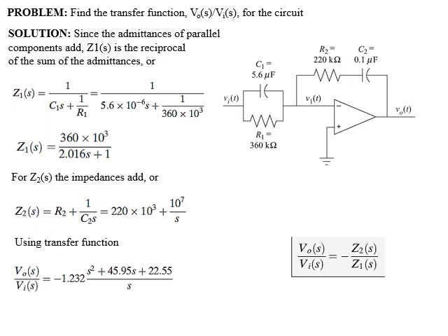Dear students, now with the help of an example, we'll get the inverting amplifier more clear. In this example, you have to find the transfer function V0 of S over Vi of S for the circuit given in the figure. If you look at the input path, the input impedance consists of two components, a capacitor and a resistor. Similarly, the feedback path also has two components, a resistor R2 and a capacitor C2.